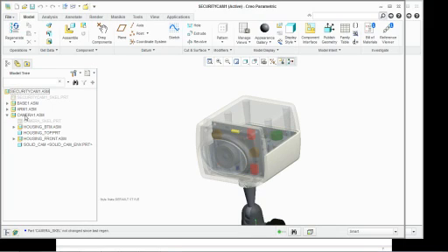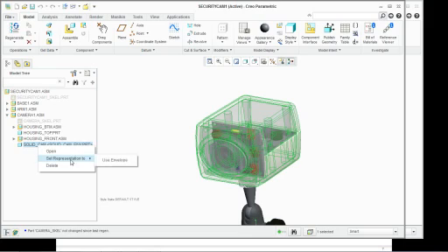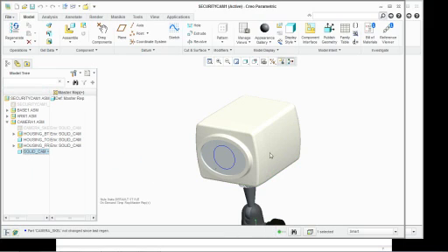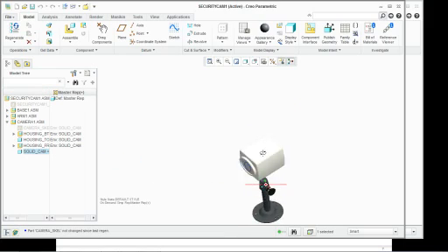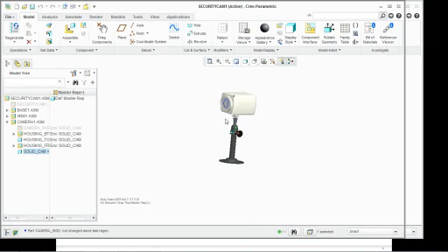So I'm going to come in here and expand out my camera1.assembly. I'm going to select this solid cam envelope part, set representation to envelope. Notice it did change it now. My part spins around much easier. It's a lot lighter weight.